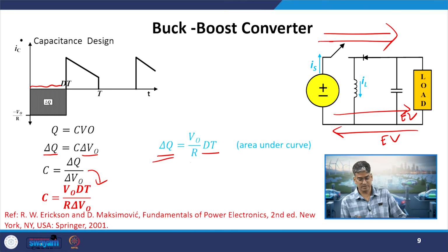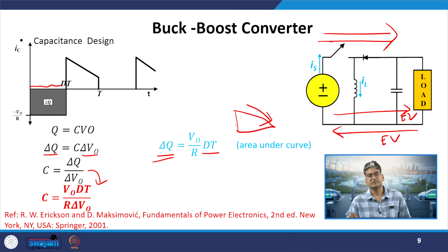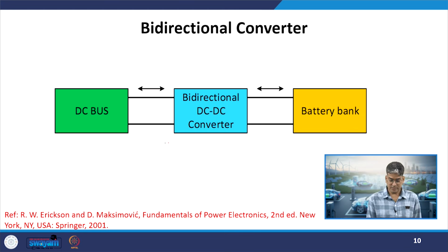Okay. So, one is during the stop case, the other example is when I am moving down hills, I will have excess energy which can be used to charge my battery bank. For this type of application we require the converter to be bidirectional, that is, the power should flow from the input to output or from the output to the input stage. This is the requirement of a bidirectional converter. The power can be flowing from the converter to the battery bank or vice versa.